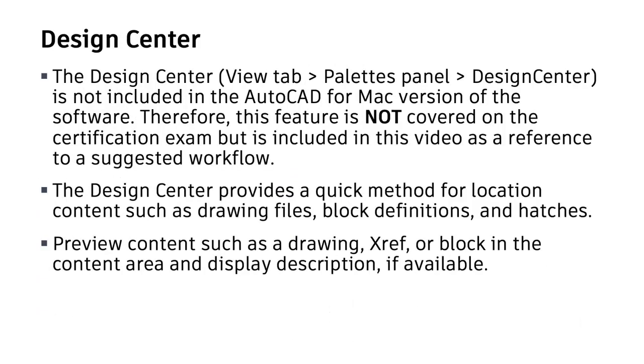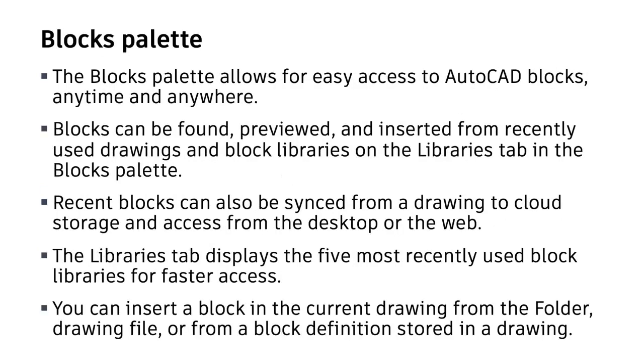For this reason, many users prefer to use the DesignCenter in AutoCAD. They use DesignCenter to bring the blocks into their active drawing. You can also use the Blocks palette in newer versions of AutoCAD as well. It performs in a similar way to DesignCenter.